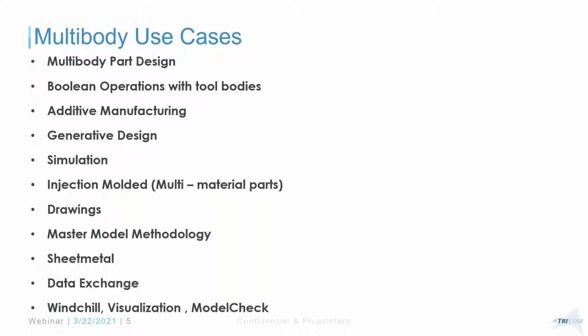However, starting with Windchill 12 and Creo 7.0.2.0, there is an option where you could designate those multiple bodies as .prts, so that after check-in, if you use the Windchill WT parts or your part structure, it can contribute to that. But again, that's new in Windchill 12, right?